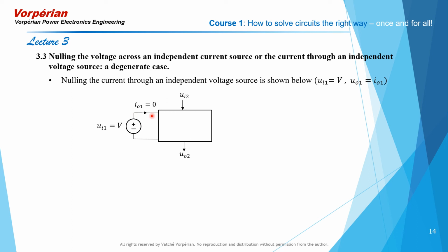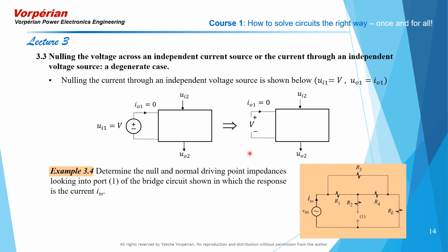And now I'm going to say with these two excitations, input 1 and input 2, I can null this current here. I can reduce it to 0. When you do that, this is equivalent to opening this branch here. So whatever equations you write for this circuit and whatever equations you write for this circuit are identical. Again, this is by the substitution theorem.